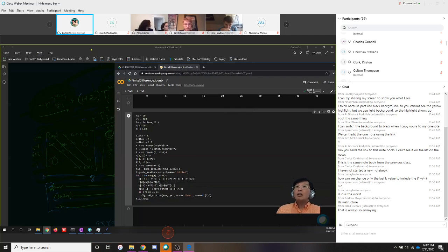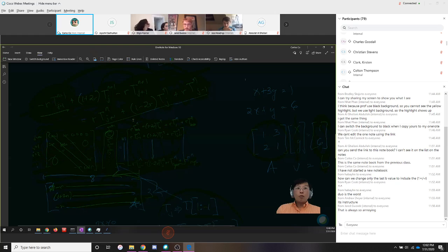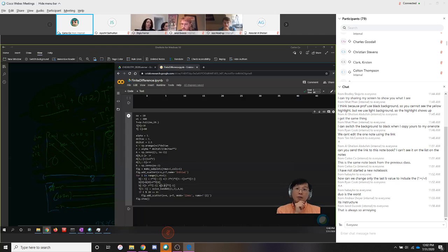Why is that? Let's take a look here. If we are at the last temperature, this is your T -1 corresponding to the last temperature. Notice you cannot go further than this. So this value gets added in there. This is the temperature for the last node, and this is the temperature of the node two nodes back, that's your -2. If you look back at the code, that's what we did there. So this takes care of those last two temperatures.